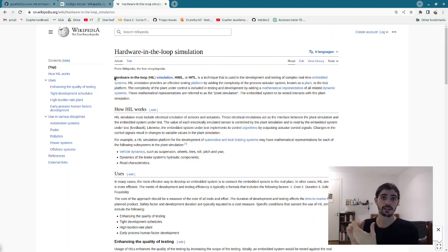Before you actually set it out to fly and maybe break it if it's not completely tested, you might want to have it affixed to some sort of gimbal where you can move it around and incline it and see how it reacts to these external impulses, because it probably has an accelerometer and gyroscope, and you want to see that the drone's interpretation of what's happening matches what it's actually experiencing.